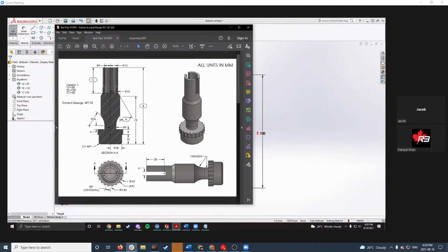But these cuts and this cut here, to me, it's much easier to deal with afterwards, especially because these cuts look like they're cutting in an up and down fashion versus this view is side to side. So you can't really do any features in the other direction when I'm sketching on this view. So I'll show you how I'll add those other features after I revolve this sketch here.